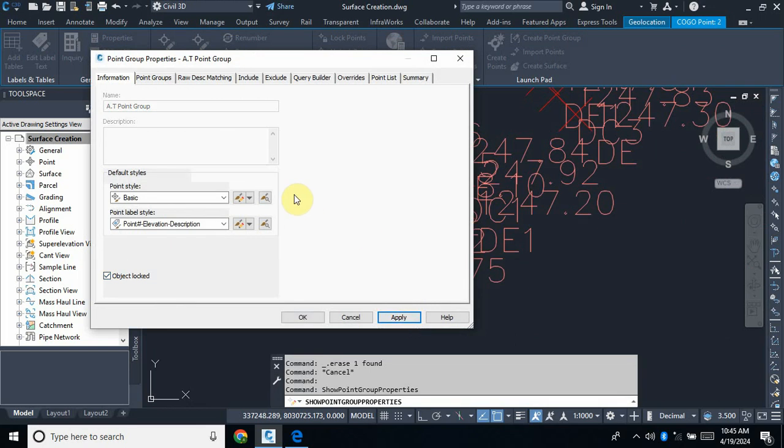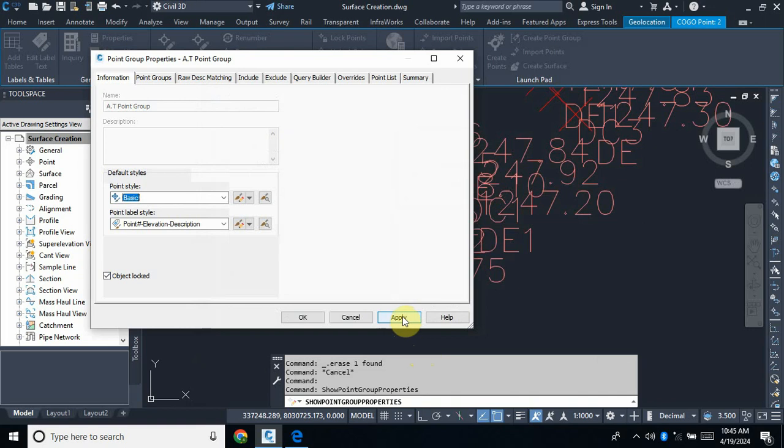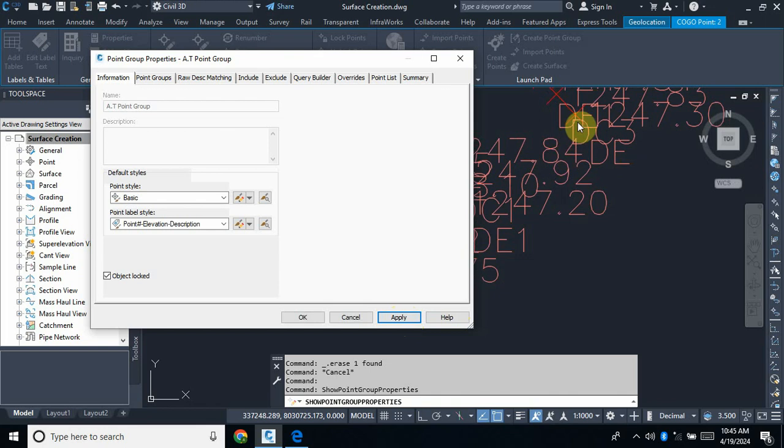Then from there we want to reduce the point size of our marker, so you simply come here, then you say edit current selection. Then from there, as you can see, we are on marker, so we are using this marker. So what you do, you come on to marker size, then you can reduce it maybe to 1.5. You apply, you click OK. Then from there you can click apply. So as you can see, the point size of our markers have reduced from 2.5 to 1.5.